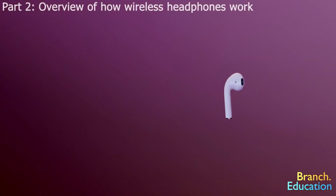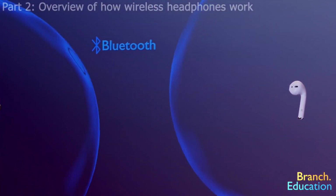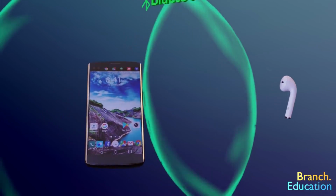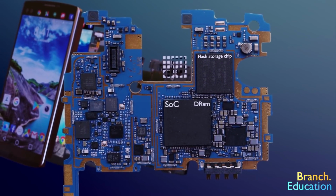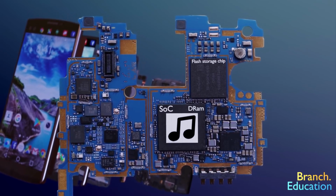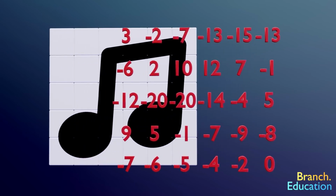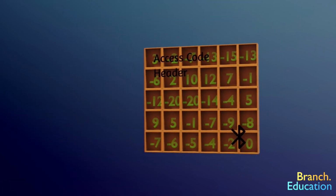Now that we've seen everything that's packed inside these earbuds, let's talk about how they work. When you turn on your already paired wireless headphones near your smartphone, a Bluetooth communication channel is established in order to send information back and forth. As soon as you start playing music or a podcast, your smartphone grabs the audio data from its flash storage chip, decompresses the audio, and stores it in your phone's working memory. This audio is represented digitally as a long set of numbers, and in order to send it to your earbuds, your smartphone compresses and divides the information into packets according to Bluetooth specifications.